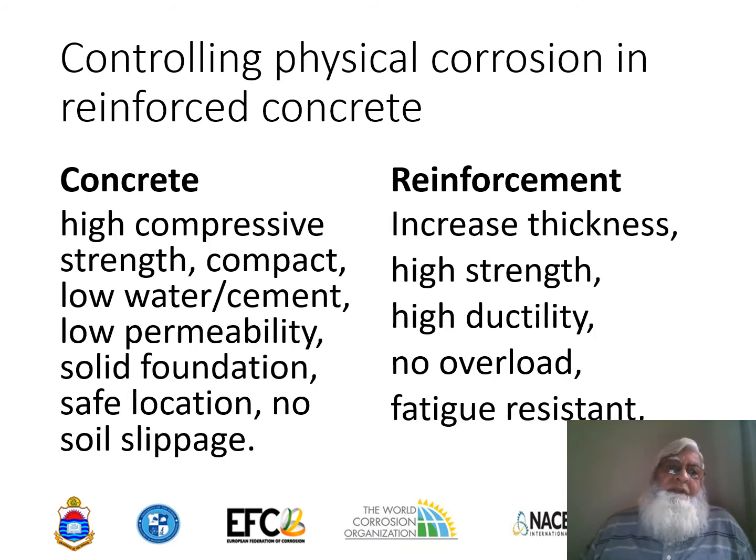Controlling physical corrosion in reinforced concrete is done by using high compressive strength concrete, making it more compact, and keeping the water cement ratio and permeability low. Have a very strong foundation, put the buildings at a safe location, and ensure that the foundation is properly compacted so no soil slippage takes place. Otherwise, the entire building can collapse. The same is true with the reinforcement.